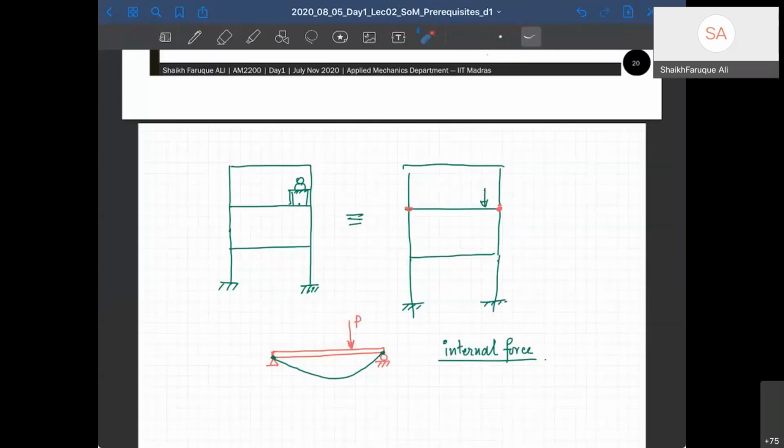In a design criteria, you have to find from that maximum load, what is the external load that it can have. Okay, in this case, you can find out what P is here. So you know what is the shear force here, right? And what will be the shear force here, right? Let's say if this is A and this is B, then this should be P into B by L, and this should be P into A by L, right? You have to remember those things. So you can see that different directions have different loads. Therefore, this side of the structure will have lesser load.